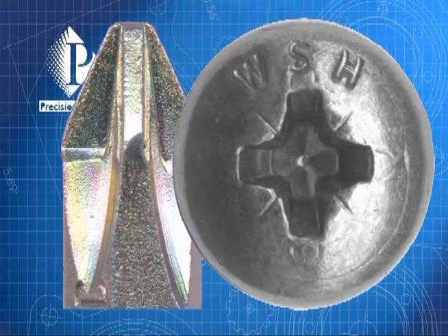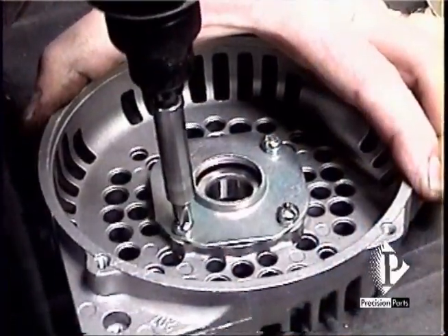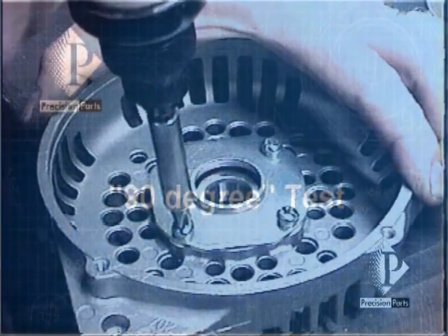When looking at the fastener, you can tell a Phillips from a posi drive by the markings present on the posi drive. When you have selected the proper bit for the fastener, whether Phillips or posi drive, the bit will rest solidly inside the screw, and the rundown will be smooth and solid.